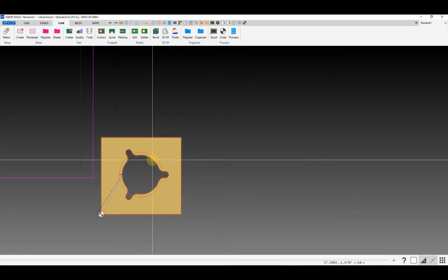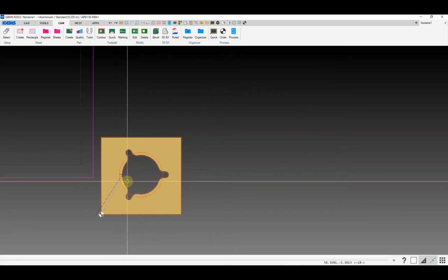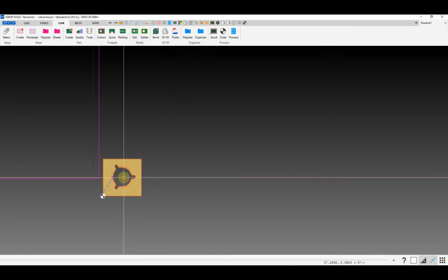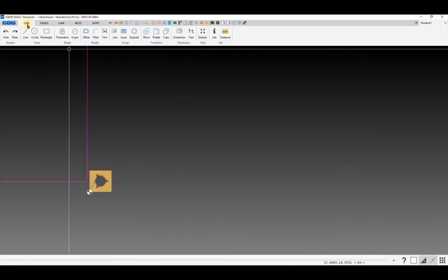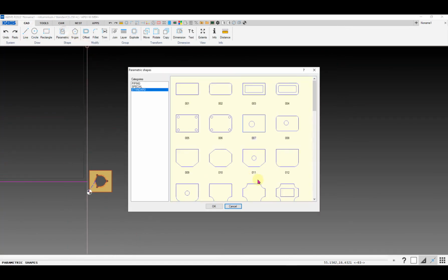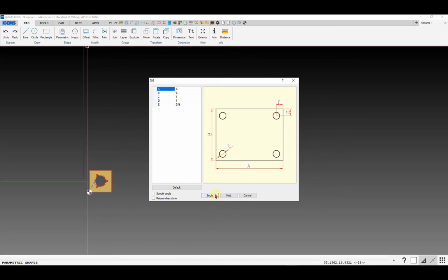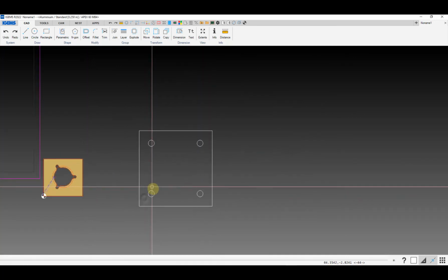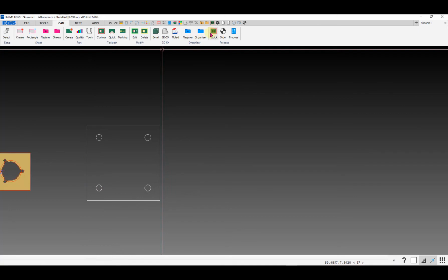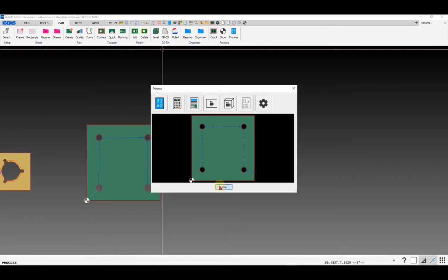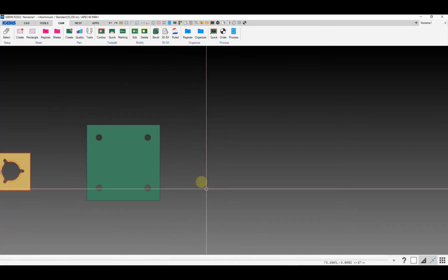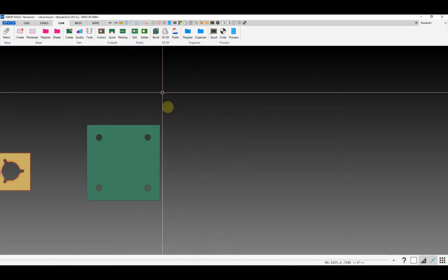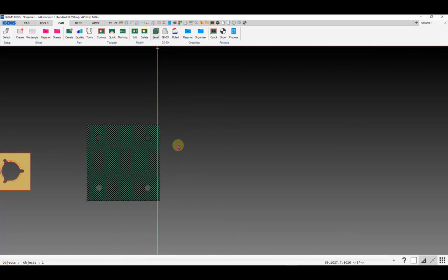So you can adjust how many height setters it does with those various settings, the sheet wise, part wise, or the stamping radius. You can also force it to do a height setter on a particular cut if you really want to make sure that you're at a particular height for a cut. So I'll just do a part here like this, and I'll do it quick, but I'm just going to delete all those and take this into 3D5X through this bevel option.